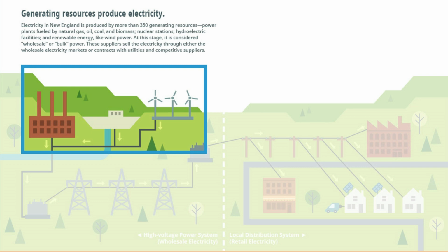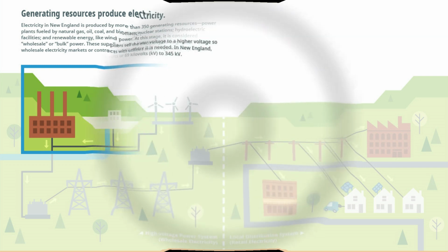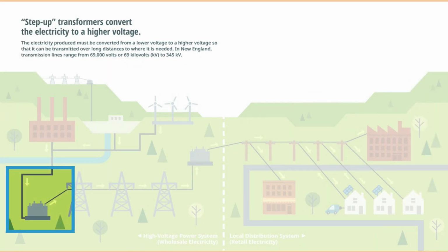If the deviation between the grid time and the universal time of the atomic clocks amounts to more than 20 seconds, the frequency in the grid is adjusted accordingly.